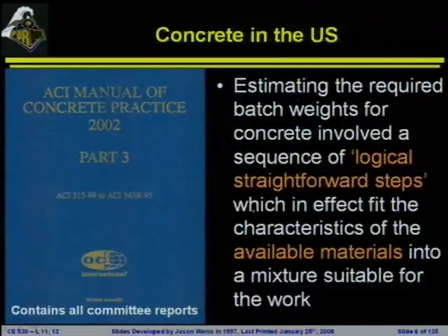Now, the authority, the group that makes the rules, is ACI, and ACI has a lovely series of committee reports. They will stack up and go about 9 1/4 inches wide on your bookshelf. There are hundreds and hundreds of committees on things that you never thought people could be excited about with concrete: lunar concrete, different types of concrete, and definitions for concrete. There are committees dedicated to this. ACI 211 is the committee dedicated to mixture proportioning. Now, the ACI committee that almost everyone in here is familiar with is 318, because that is the building code.